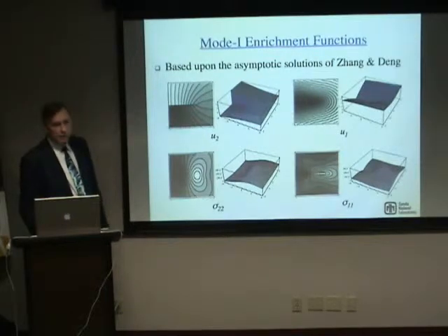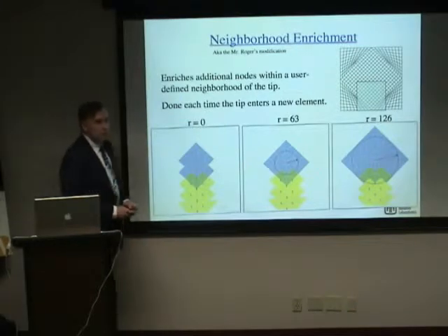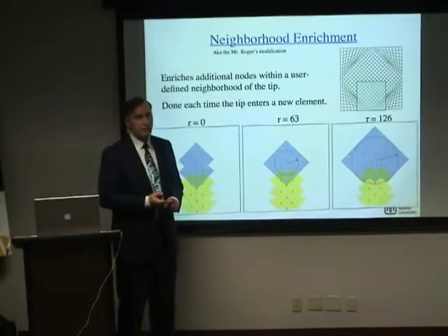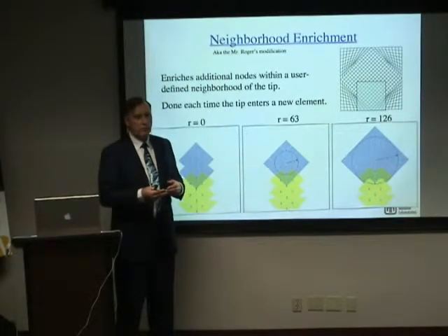What is the exact point of these basis functions? Okay. They're derived for a linear, elastic, isotropic, homogeneous domain. And so you could use the basis functions to satisfy different boundary conditions for this problem, but in particular you could adjust them to try to match what you get for the separation and the traction at the interface.